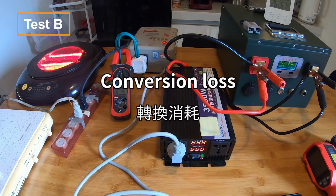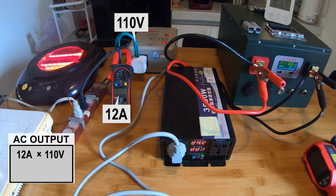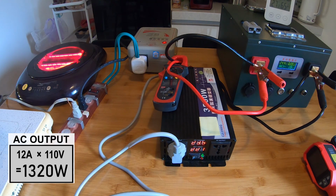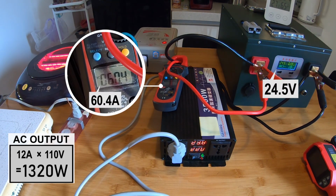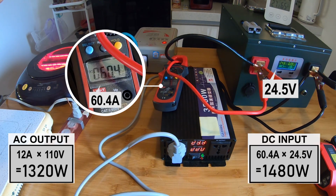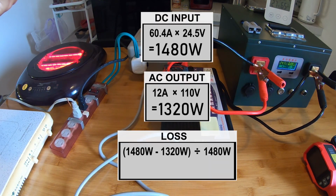Test B, conversion loss. Maintain the 12 amp AC power supply. The wattage of the battery input to the inverter is approximately 1320 watt. Using a current meter to measure the inverter input, the DC current is about 60.4 amp and the voltage is about 24.5 volt. The actual input wattage of the inverter is about 1480 watt, compared to the actual continuous power consumption of 1320 watt at the same time. The difference in wattage is the conversion loss of the inverter.